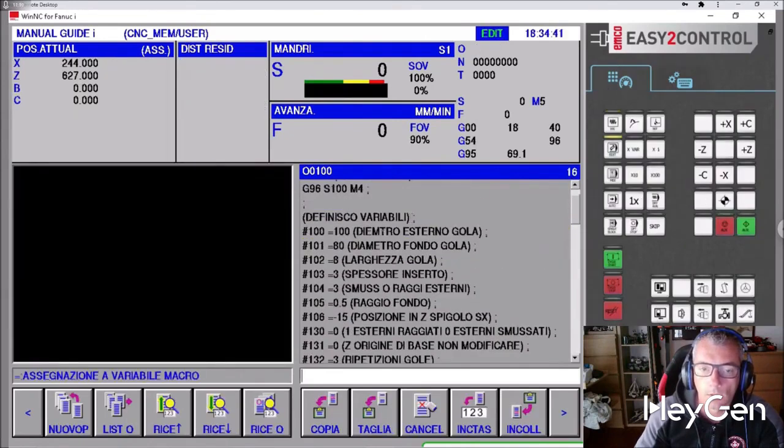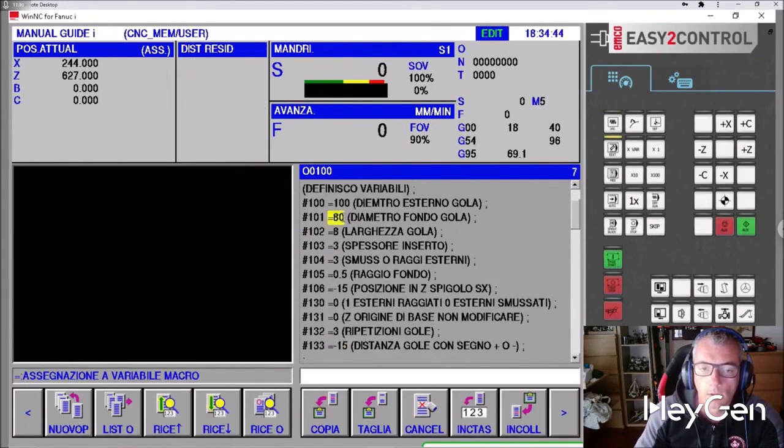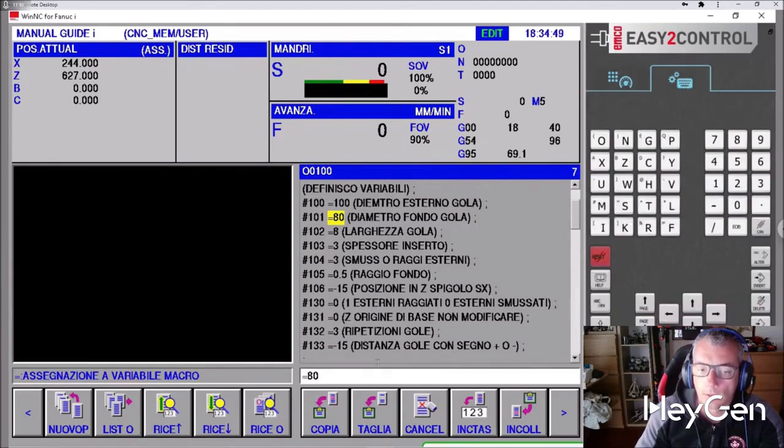I'm going back to my main program, and I'm currently telling it to set it to 70. We are focusing on ensuring that the grooves are not only deep but also sufficiently wide to meet the specified requirements. The target width for these grooves is precisely 5 millimeters, which is crucial for the design. In addition, a chamfer of 1 millimeter is deemed more than adequate for the intended purpose. The process will commence from a starting point of 10, ensuring precision and accuracy in the measurements.